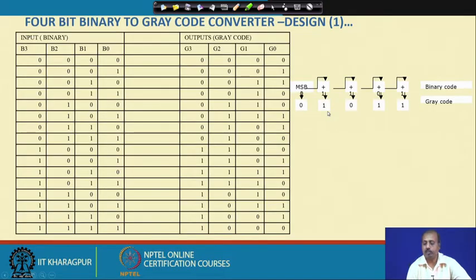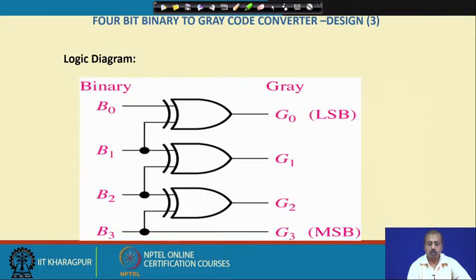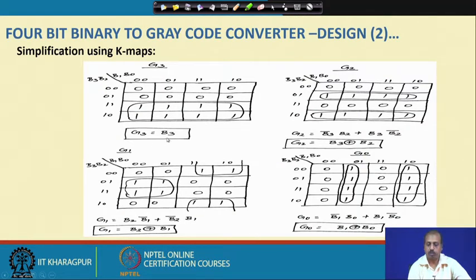You see that here also the basic definition of gray code is like that, and the corresponding Boolean function is also leading to the same thing. So, you can very easily draw a logic diagram which can convert a 4-bit binary code into gray code, where B3 will be directly copied to G3 as per this equation, G3 equal to B3, G2 equal to B3 XOR B2.